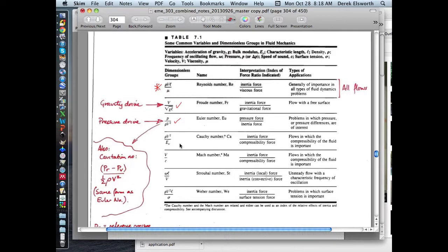And the other way of writing this, if you remember, is that our acoustic velocity is equal to what? The modulus divided by the density, square root. Maybe the second or third time we met, we talked about this number and how quickly your voice reaches me or my voice reaches you. I screwed up the calculation and worked out that the speed of sound was 10 meters a second. Actually, it's something like 300 meters a second, because I think I used the density of water instead of air. But anyway, this is the velocity.